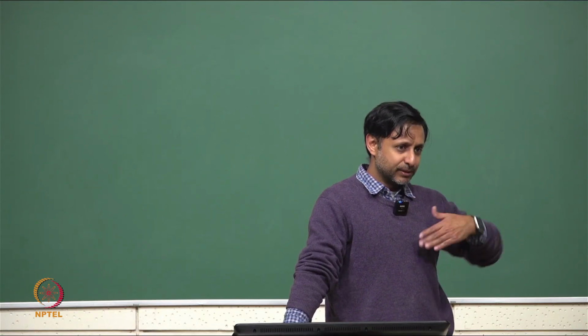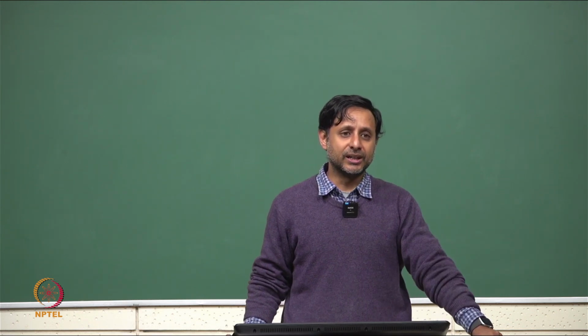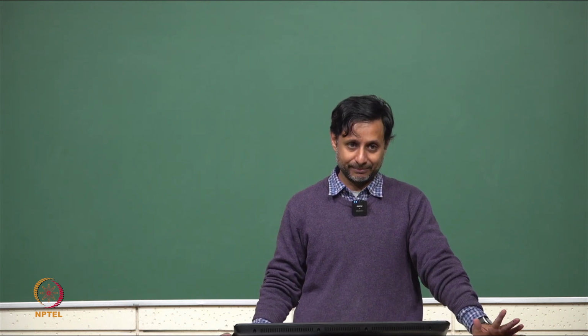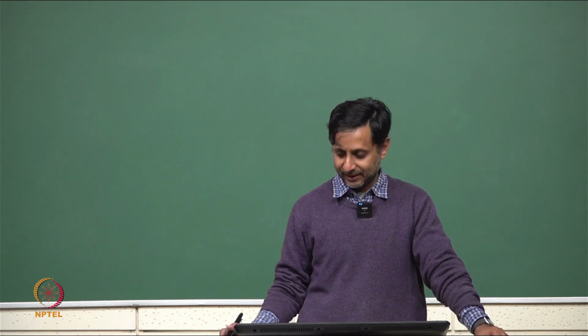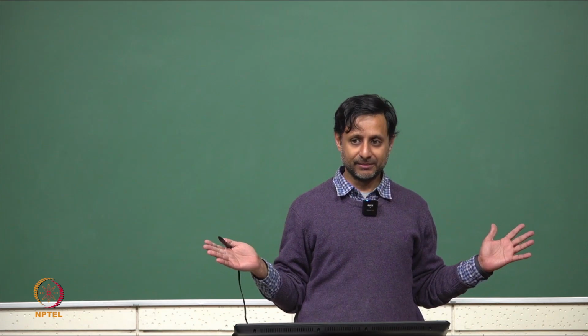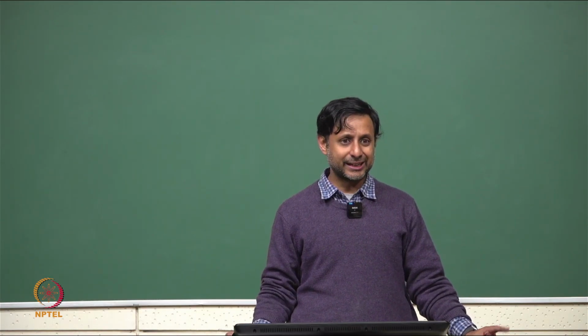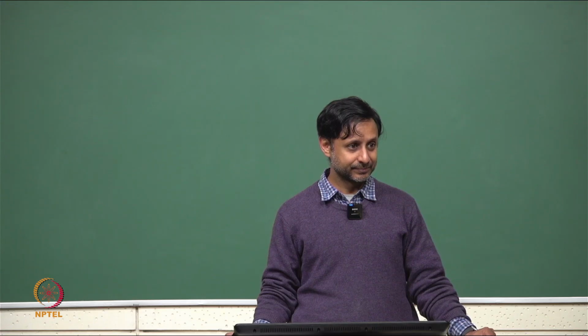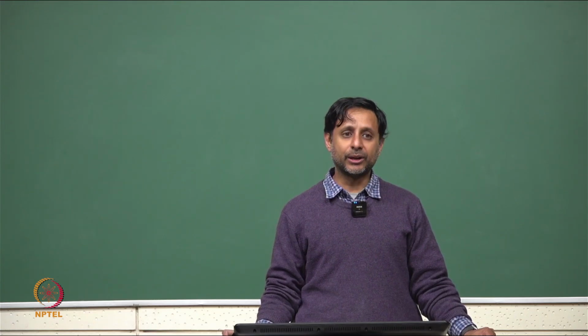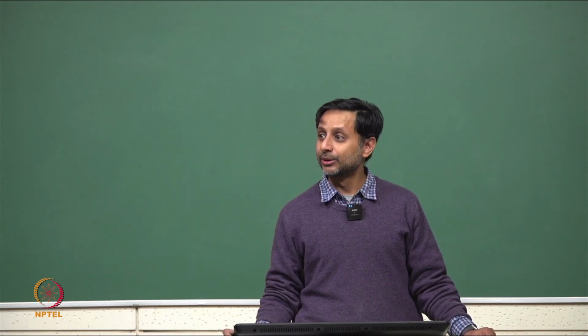Before the second last step, you are only going to worry about the complex phasor. The phasor is the complex number that is in front of e power j omega t. The phasor is rotating with time, but we are not going to worry about that. We are only going to worry about what it was at t equal to 0.